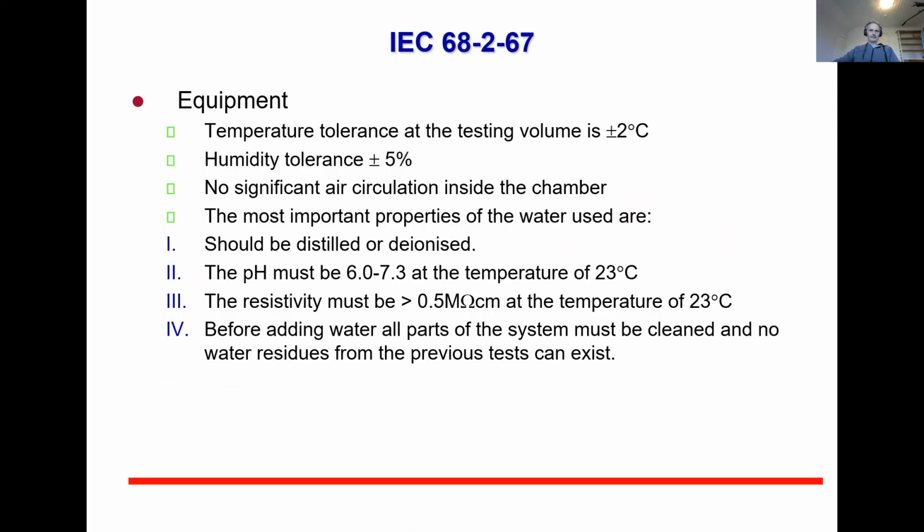Then for the water itself, which is used to make the humidity. Of course, normal tap water you cannot use. It should be either distilled water or deionized water. And here are a few requirements. The pH must be between 6.0 to 7.3